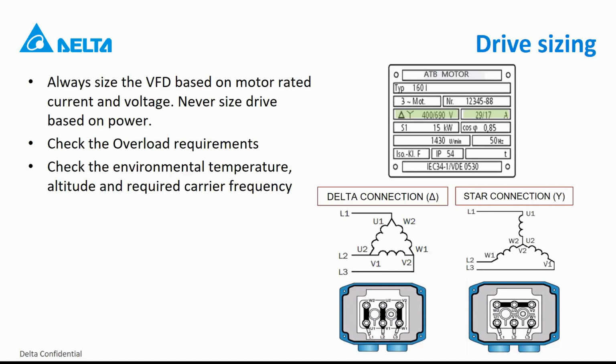This is something which you have to keep in mind for basically any electronic device, not just for variable frequency drives. But what is specific to drives is the carrier frequency derating. Of course, it makes sense that if you use a higher carrier frequency, then the drive is working a lot more and generating a lot more heat. So if you need to use a carrier frequency which is above the rated one of the drive, then we also have different graphs in the user manuals which you can consult to see which derating is actually needed.